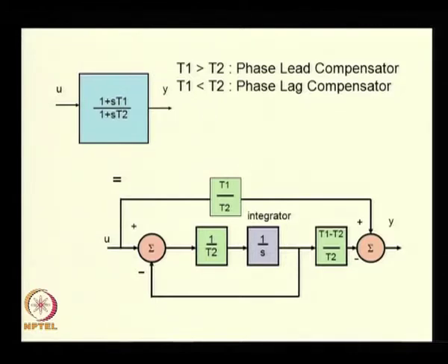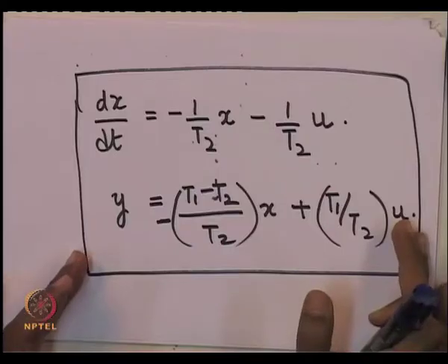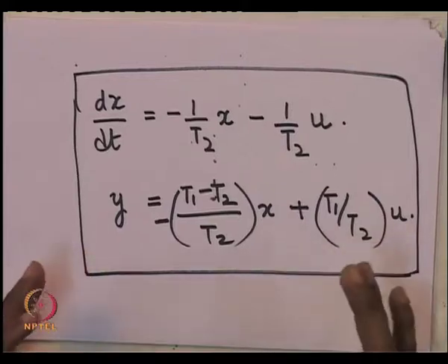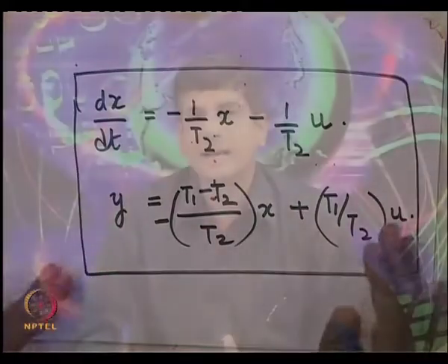But working with the state space equations and differential equations is more convenient later on when we will be doing numerical integration as well as linearized analysis, eigen analysis of the system. It is better to write everything in the state space form. But typically what you will be given in most of your manuals and worksheets of your synchronous generator excitation system, you will find that the block diagrams will usually be in this form, using transfer function blocks.